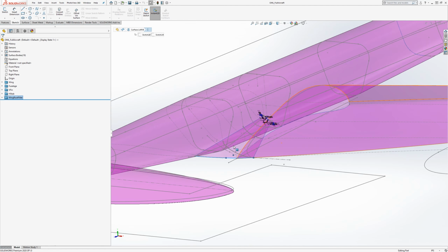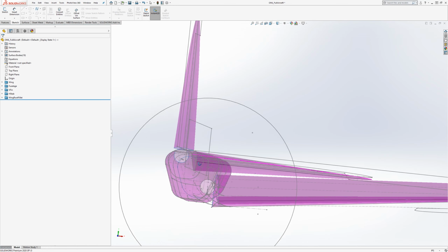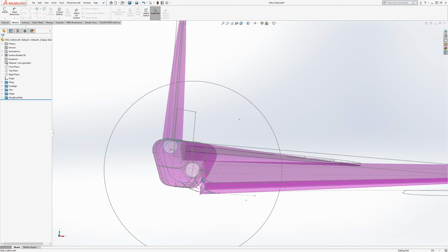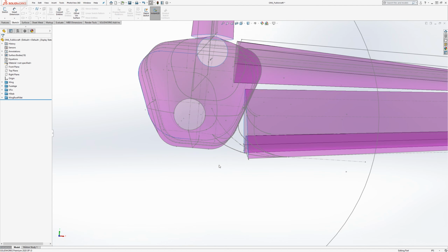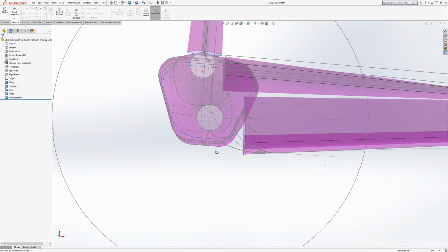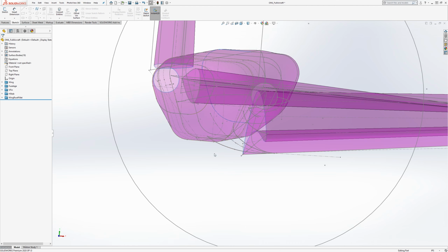So we could even imagine not having any fillet, and in that case we could actually construct the aircraft with this gap here, and the airplane would still fly. It would just have a bit of interference drag and vortex things going on under here.